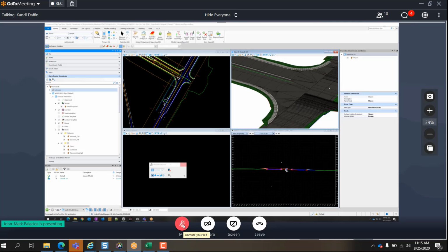if you're doing quantities by end area, you have to fill out the table by hand. If you use the surface to surface earthwork and apply the item types and generate it with quantity takeoff manager, you're going to get a more accurate quantity. And I'm thinking that they should accept the quantities from QTM. And if you need backup, you can show the average end areas, but